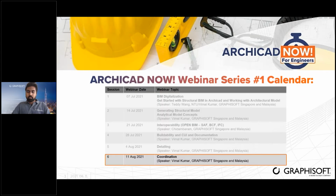All right, so let me do a short recap of what we have been seeing in this webinar series. On the first session, we were seeing how to create a project and set a project for structural BIM modeling in Archicad based on the information that we get from the Archicad model. After that, on the second session, we were creating the structural BIM components like beams, walls, slabs, columns, foundations inside the project. And then we were also trying to create or generate the structural analytical model within Archicad using the structural model generation rules.